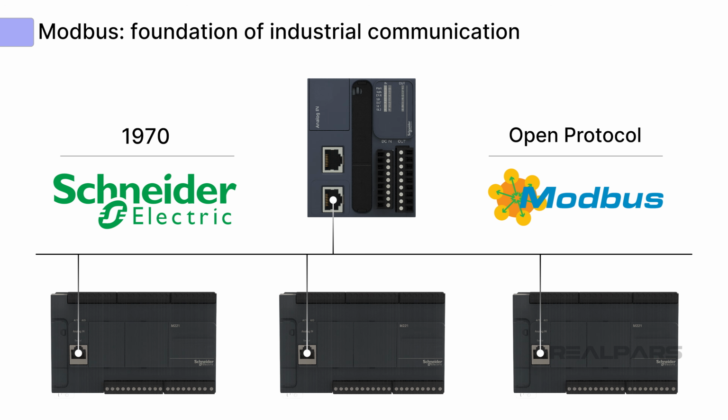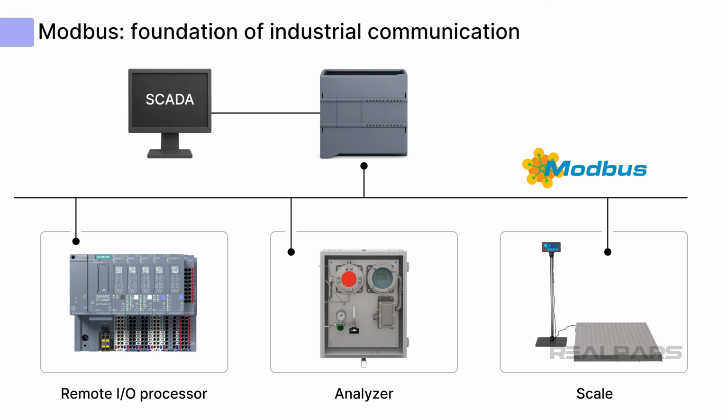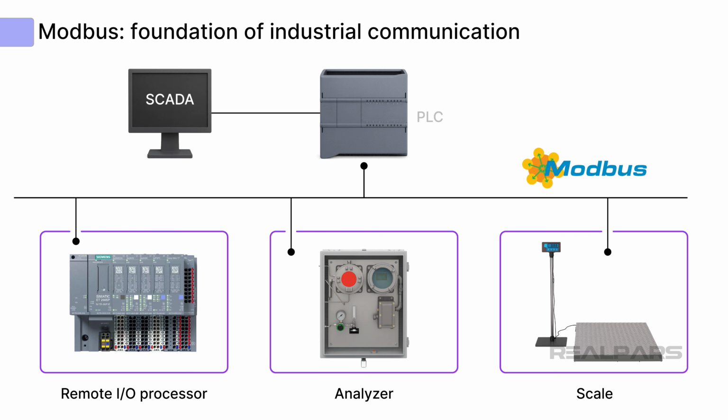Modbus is a simple open data communication protocol developed by what is now Schneider Electric in the late 1970s. Although specifically designed for use with its own PLCs, it has become widely used as a general communication protocol for communicating between control system components, such as remote I/O processors, analyzers, scales, as well as PLCs. Modbus uses a client-server architecture and can be used with various communication protocols, including TCP/IP.